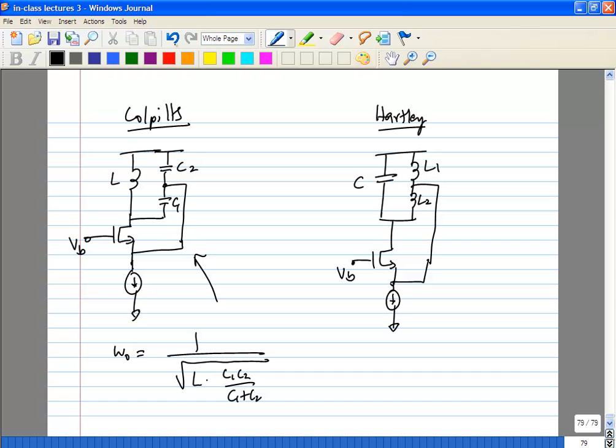Okay. So we know that the oscillator is a large signal system, because the oscillation amplitude is going to be probably several hundreds of millivolts to probably a volt, and could be higher. So what we'll do first is find out the large signal transconductance of the transistor, in something similar to Colpitts in an oscillator configuration. Then we'll use that in the Colpitts and find out what the circuit looks like and so on.